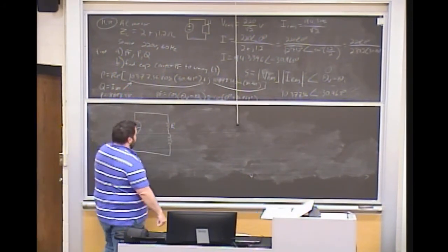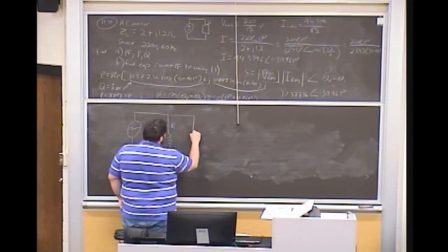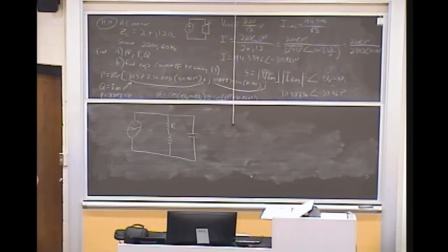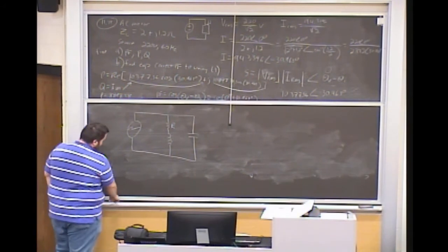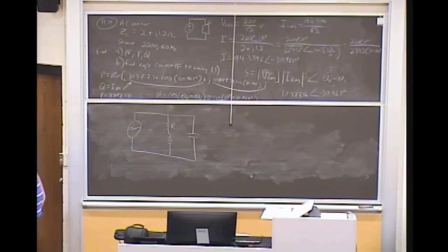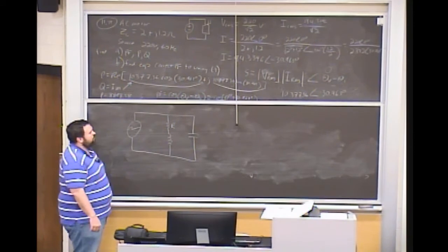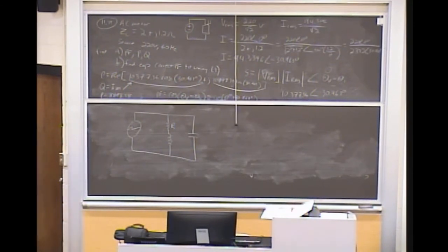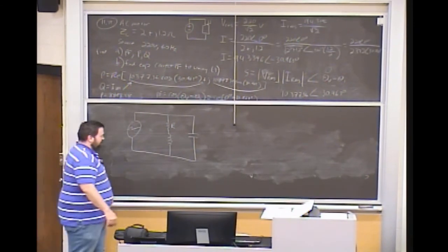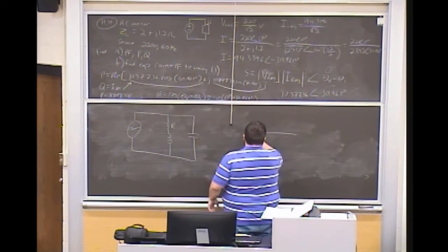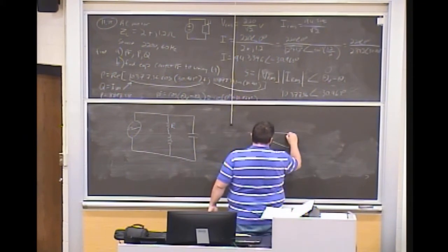And what we can do to change that power factor is we can pick a capacitance to put in parallel there. And effectively what we're doing is we're picking a capacitance so that ultimately we nullify the effect of this inductance. And what that does is it really just adds a vector to kind of bring this power from something that is away from the real axis.